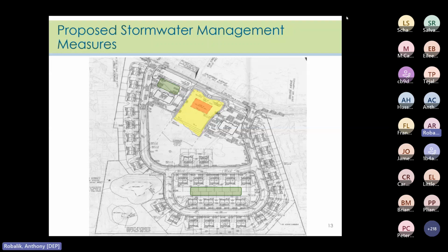As was mentioned before, they are constructing an infiltration basin. The infiltration area is only the 6,000 square foot area at the very bottom of the basin that's highlighted in that orange color. The rest of the infiltration basin in the lower portion is grass, and the upper portion extending back is remaining as woods. So in the case of the 100-year storm event, runoff filling the basin is going to reach back into the wooded area and use that as detention.